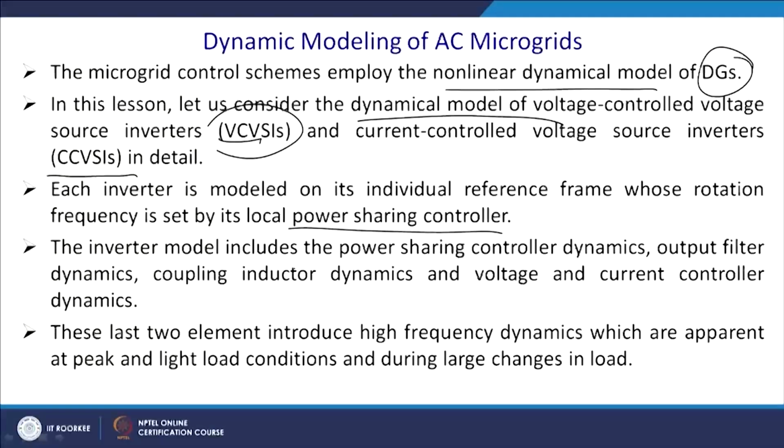The inverter module includes power sharing controller dynamics, output filter dynamics, coupling inductor dynamics, and voltage and current controller dynamics. These last two elements introduce high frequency dynamics which are apparent at the peak and the light load conditions during the load change. Let us explain what it is basically.